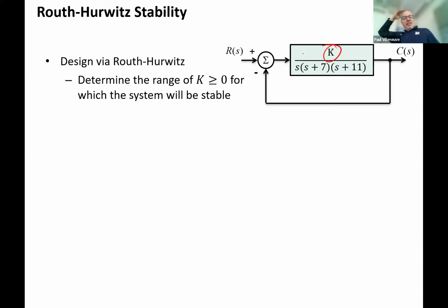By the way, there's somebody in the class who's going to be working in the process control industry. If you do legit control systems from a process control perspective, anybody know what the systems work on? How do you communicate to end devices? Some stuff now is switching over to all fiber optics, so they'll use just digital communication. But a lot of people are still relying on the tried and true. They use 4 to 20 milliamps. So 4 would indicate no output. 20 milliamps would indicate 100% output.